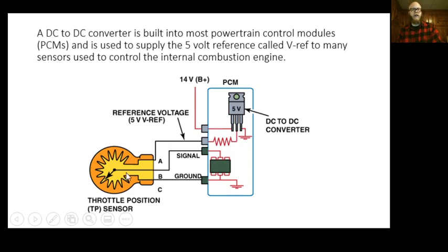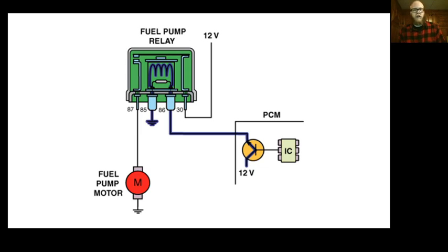as I get a varying voltage back, right, this wiper would be dropping voltage, so I'd have 5, 4.5, 4, 3.5, 3, 2.5, 2, 1.5, 1, 0. So as that wiper moves back and forth, and I get the signal to this integrated circuit on the inside, then I would know that 1.5 volts means that I'm at, let's call it 15% throttle, and it means always 15%. It doesn't mean anywhere from 10 to 20%. No, it means exactly 15%, and that's huge. It's very, very important.